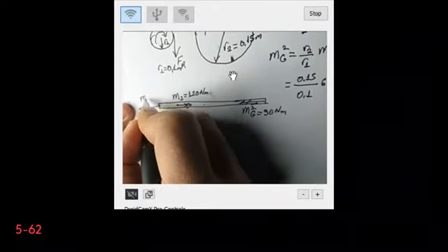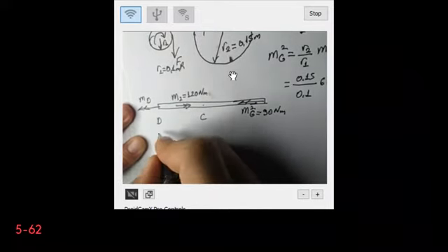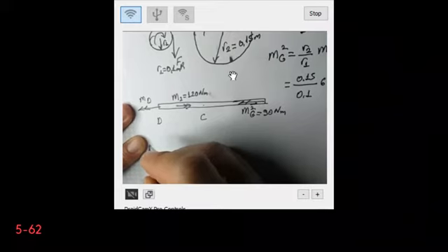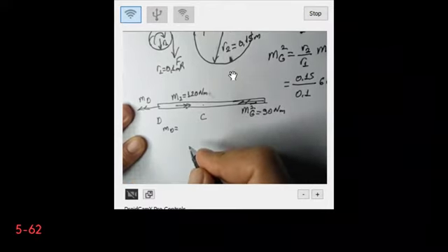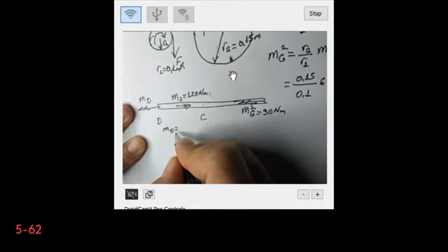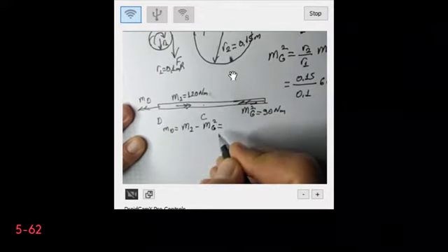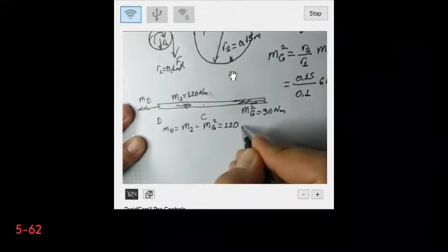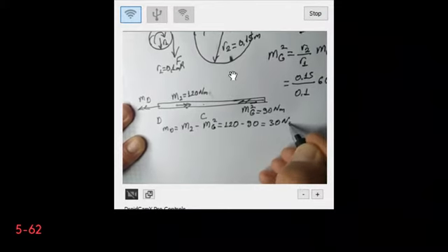Let's say that this is MD. Now I can calculate the MD easily. Certainly I choose an arbitrary direction, so I don't know the direction of the MD. So MD is equal to, in fact, M2 minus mg2, because the sum of the moments has to be equal to 0. This is 120 minus 90, which makes 30 Newton meters.